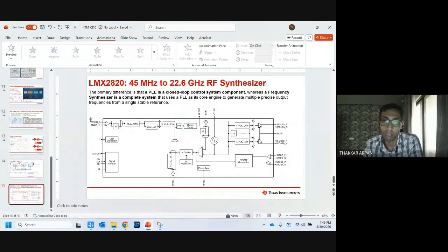Okay. So let's say you want 10 gigahertz of output. Instead of that, you can end up giving 9.9 gigahertz of output. And that is a variable frequency. Across temperature, it is going to vary, because whatever circuit you are going to make, you have to basically have the same stability as the crystal. If you try to make it with discrete components, it's going to end up with a few percentage of change. So 1% means 10 raised to 4 ppm. So 10,000 ppm. So you understand, right?